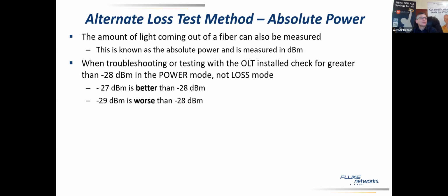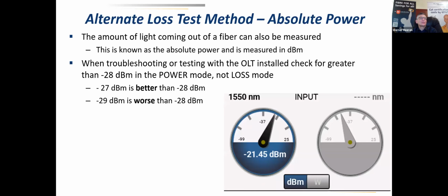That's completely incorrect. Also good to know is, -27 dBm is better because it's more power than -28 dBm, although the number looks bigger. But it's less negative. This is more negative. So this is more powerful. This is more power, so this is better. It's sometimes confusing because of the negative sign and the value itself. What is now better? So it's very important to see these differences.